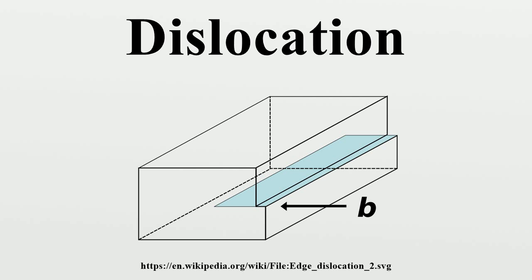Dislocations, slip and plasticity. Until the 1930s, one of the enduring challenges of materials science was to explain plasticity in microscopic terms. A simplistic attempt to calculate the shear stress at which neighboring atomic planes slip over each other in a perfect crystal suggests that, for a material with shear modulus G, shear strength tau m is given approximately by,